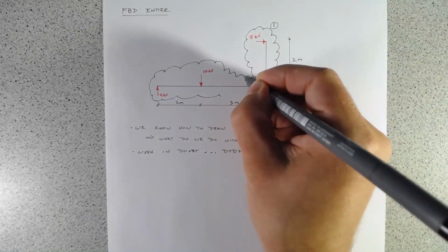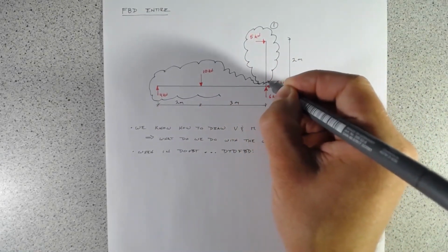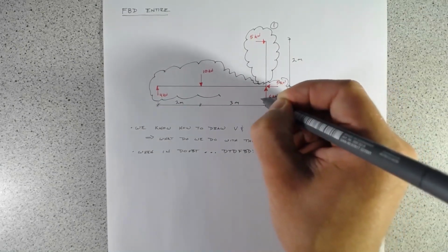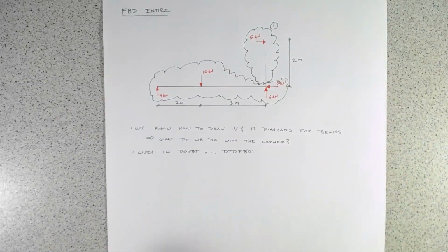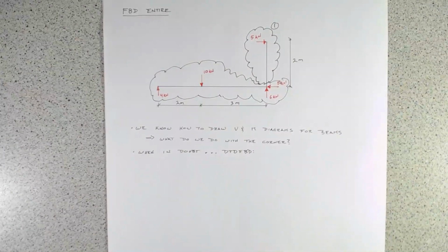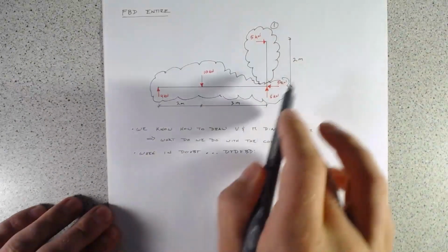And if you recall back from analyzing trusses, this is very similar to method of sections, where we're going to break down the structure into multiple free body diagrams, expose the internal forces, and then use that along with our equations of equilibrium to try and solve the problem. So if I've got these two, let's draw the free body diagram at cut 1.